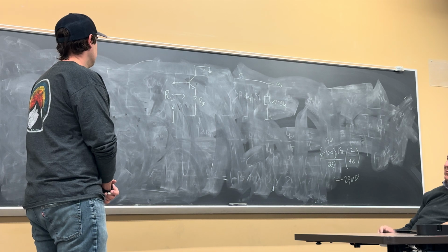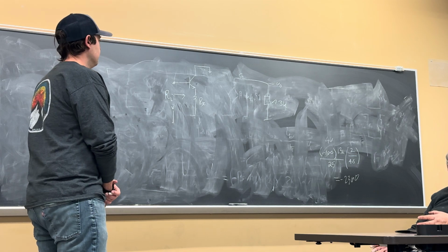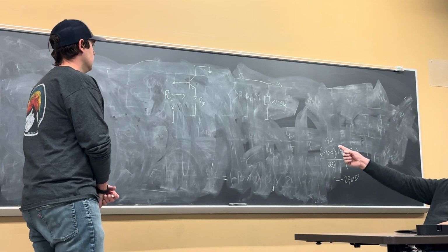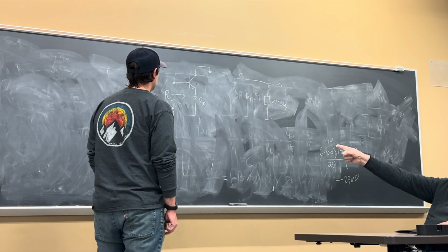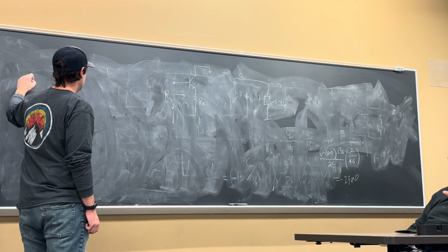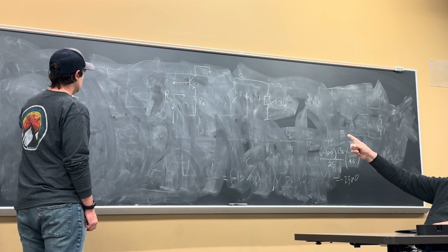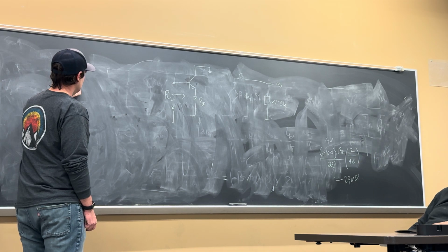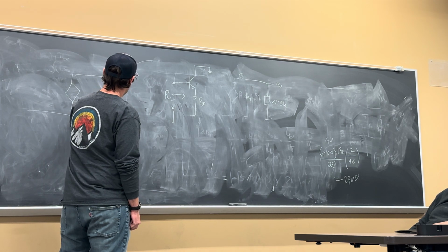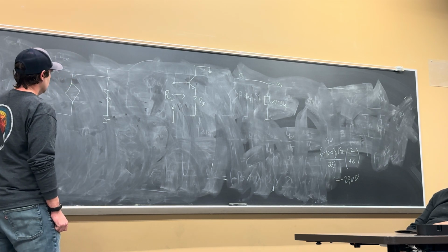All right, how do you calculate input impedance, or impedance of anything? You put the circuit, you apply test voltage, and measure test current, and VT over IT is the input impedance, right? Draw the small signal equivalent circuit for this. The input impedance is an AC phenomenon, not DC. Impedance is AC, and that's why I drew AC here. I put grounds up there. Grounded doesn't have to be, we could put the resistor if you don't want. Put the rest of the circuit in.